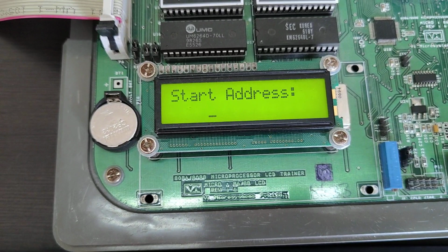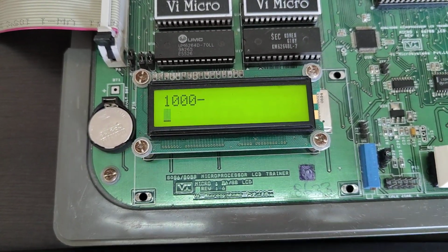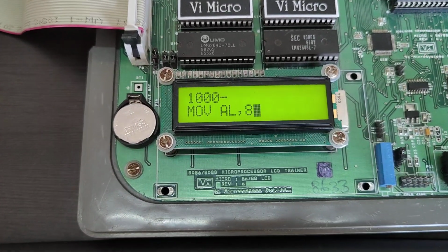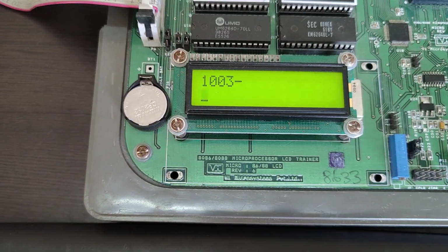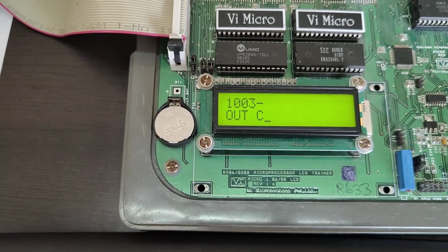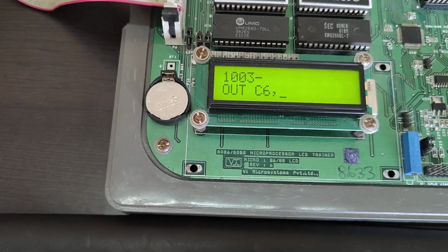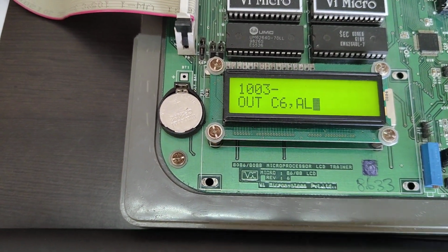Enter. Starting address 1000. Move AL, 80 to initialize your 8255. This value 80 should be moved to my control word register. So OUT C6, the address of your control word register is C6, AL. So AL holds the value 80 to initialize your 8255.